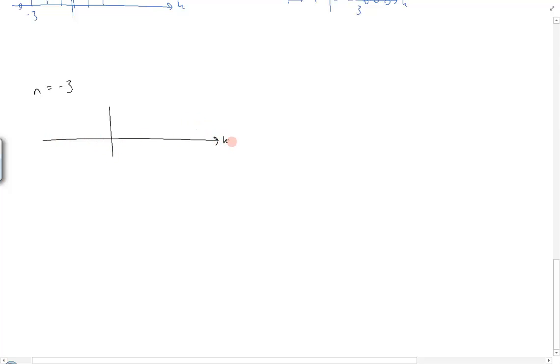So we still have our x of k, which begins at 2 and is this decaying exponential, and is zeros everywhere before that. And right below it, I'm going to draw h of n minus k. In this case, we know what our n is. It's negative 3. And therefore, negative 3 plus 3 is 0. And that means that our function looks like this. And this goes on, and it's zeros everywhere beyond.